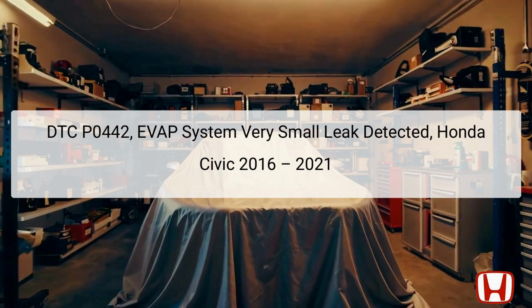It utilizes various sensors, like the fuel tank pressure, FTP, sensor, to detect leaks and ensure that the system operates efficiently. Diagnosing this code requires special tools to test for vacuum and pressure leaks, highlighting the critical nature of not exceeding specified measurement thresholds to avoid damaging any components. Understanding this error is vital for maintaining emission standards and overall vehicle performance.